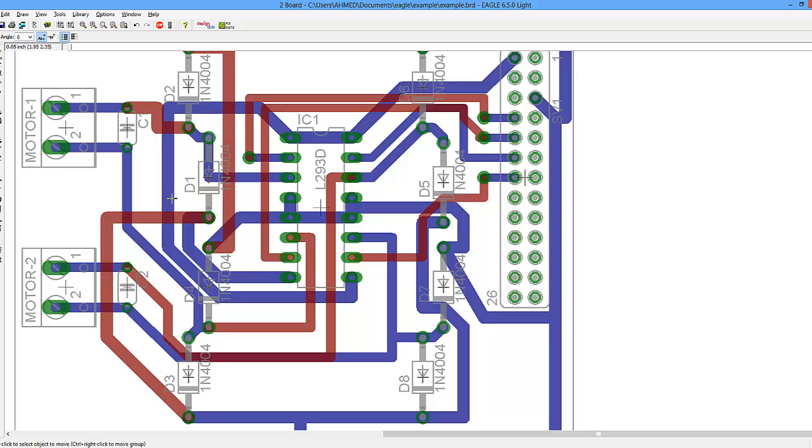Now, if you are going to solder the chip on the PCB itself, I would say you are done right now, but no. It's not a good idea to solder the chip on the PCB for a simple reason. It might get damaged, so you have to desolder it again, and believe me, desoldering a chip off a PCB is pain. So do a little more work, better than banging your head on the wall after.